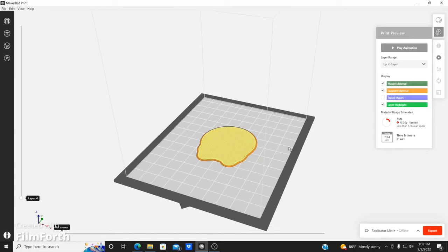And most of the time, they will do the same thing again with the 3D community, where you can do numerous combinations. You can do one for the build plate, the adhesive layers on top of it. Then you do the blue scotch tape, hairspray, glue sticks, etc. So there are numerous ways you can use it, but the cheapest one you can go for is the blue tape, then the hairspray and the glue sticks. Just in case anything else fails on your printing, so that's a heads up.